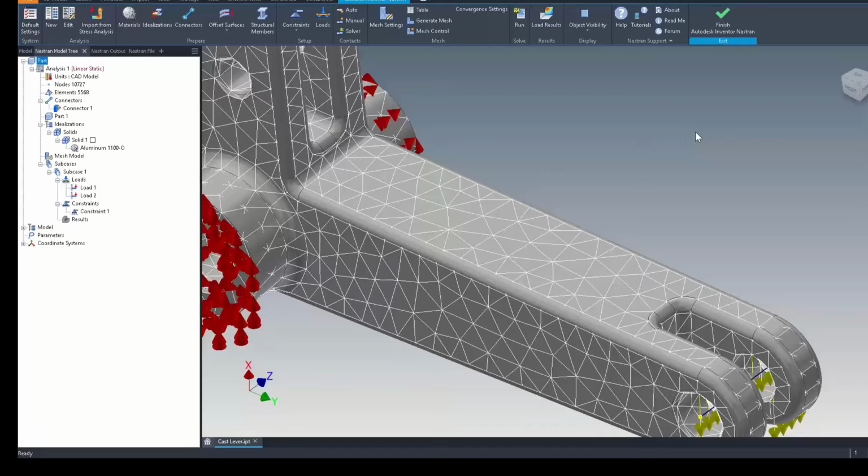When it translates into Inventor, the surfaces could have gaps. There could be surface deviations. For that matter, it may never have been a natively modeled file, and it could have been generated from a 3D scan. If it's a 3D scan, there's going to be all kinds of fun going on that surface. So this is what you're looking for, especially on imported or translated components.